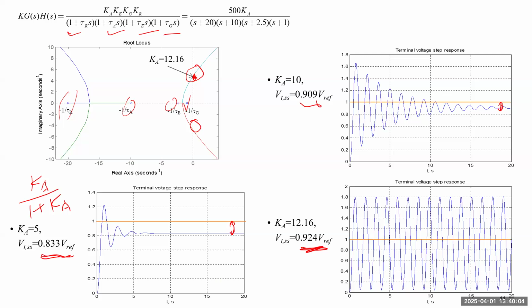beyond that value. So what you can do is add another pole. Once you add another pole, each root locus will shift. They still follow the number of formulas we taught. If I give you the location of the open loop transfer function's poles, how do you roughly draw each root locus?